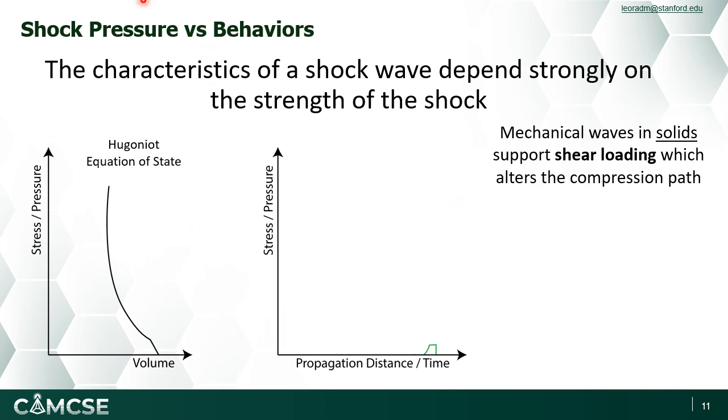So we can now ask ourselves, now that we understand how to study the shock wave, how to observe it, well, I guess we'll get to how to observe it in a little bit, but at least how to study and resolve the pressure in it, what exactly are the behaviors that we would expect from these shock waves? Turns out the characteristics of the shock wave depend quite strongly on the strength or the magnitude of that shock wave, as you might expect in a nonlinear wave like a shock.